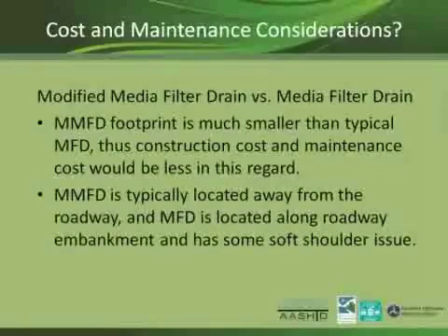And since it's off the roadway, when we maintain it, we don't have to close the lane, so there is less traffic control. So it costs less to maintain the modified media filter drain. Next slide, please.